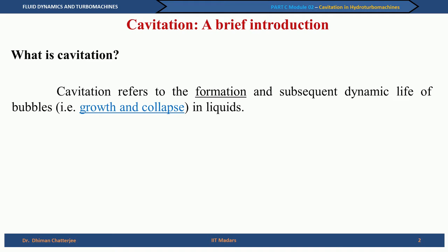If you take the example of soda water and the bubbles rising in soda water, we do see bubbles forming and the bubbles are growing, bubbles rise, but we do not see the collapse. Whereas, in case of hydroturbomachines in particular or in other applications of cavitation, it is the collapse phase which is more important. All the phenomena that are associated normally with cavitation are related with the collapse phenomena.